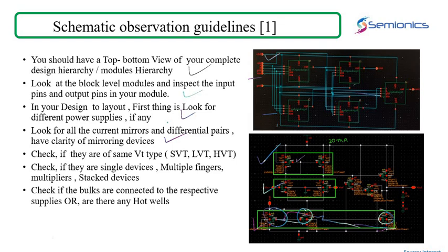So assume that you need to figure out whether this is a single device, whether it is a device with multiple fingers, or whether it is used in multiple values, or it is a stacked device. Stacked, I mean to say a bunch of devices, say 14 devices together put as one large device. 14 or 12 devices, 16 devices, a bunch of devices considered as one transistor. Okay, stacked devices.